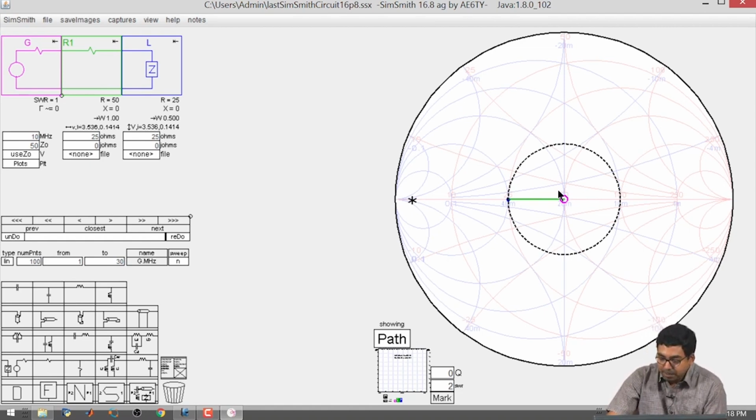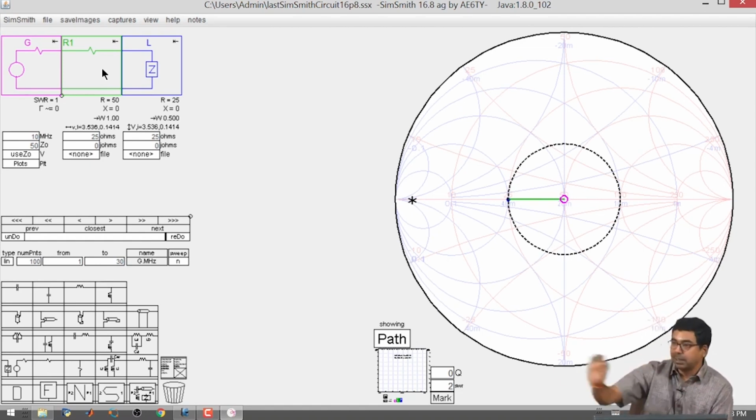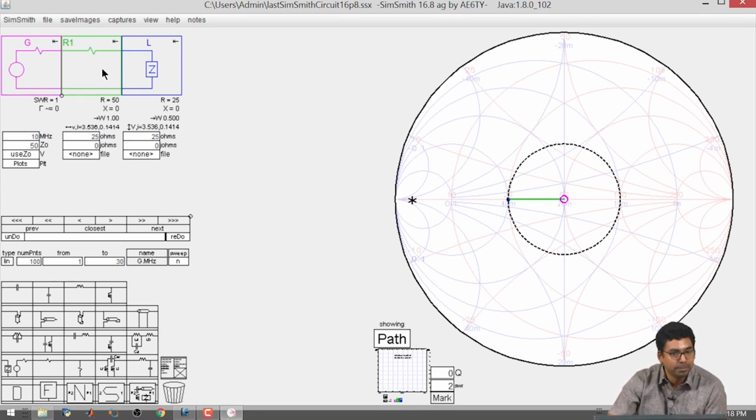We have an impedance matched circuit clearly. Unfortunately, while doing this impedance matching using a resistor, we moved along the constant reactance circle, we changed the resistor, and we know that resistors will dissipate electrical power into heat. So, which means that incoming power over here was 1 watt as seen here, half the power has been dissipated here, and only the remaining half is available for your load. So, now the question becomes, have you impedance matched and have you attained the objective?